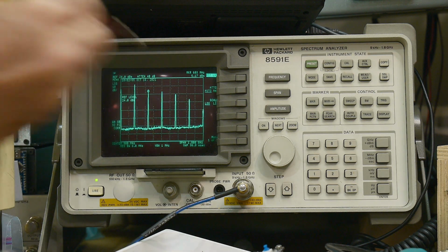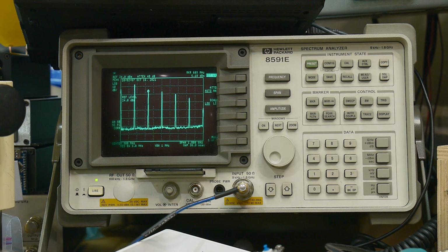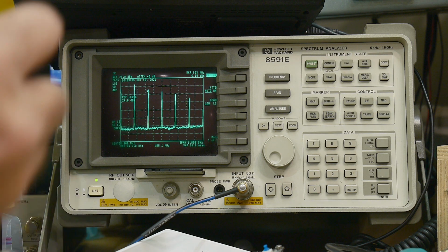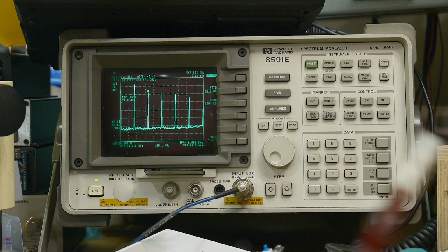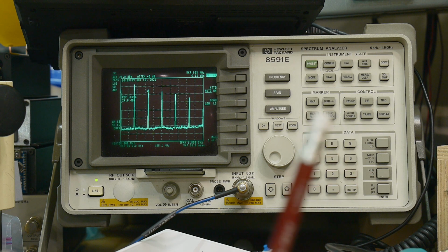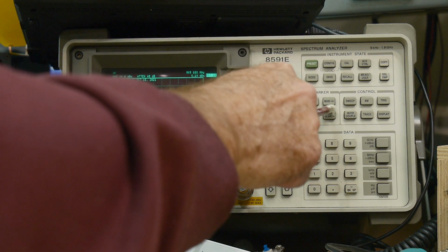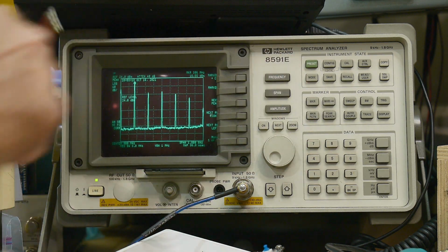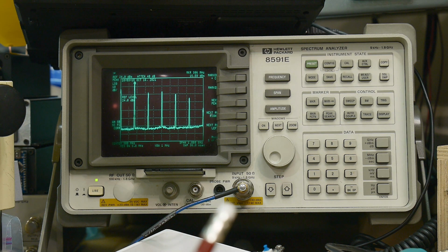So they do go down. But yeah, they're very healthy. So be aware of that. So if you're going to use this thing in high mode, be aware that you've got really high content harmonics here. Let's go back to the peak, which should be at 300, which it is. And we're getting plus 16.5 dBm. Plus 16. That's a lot.